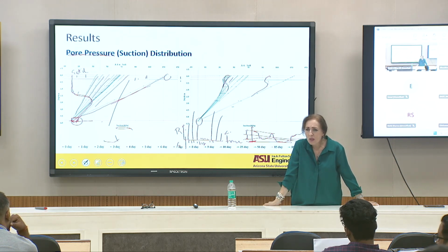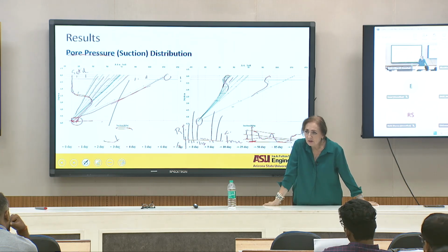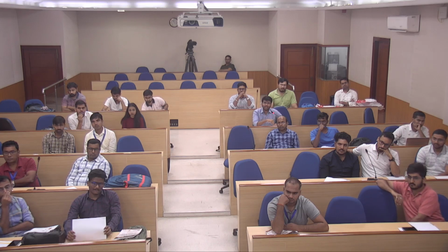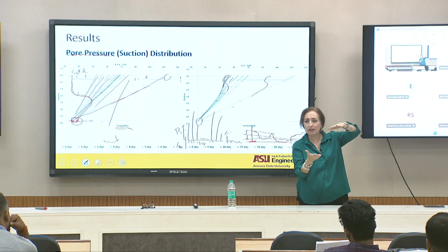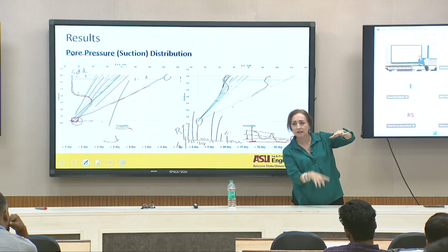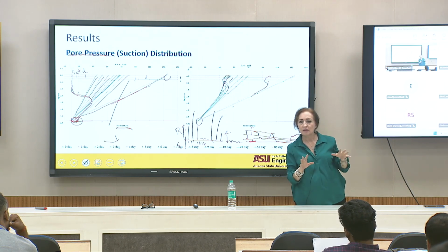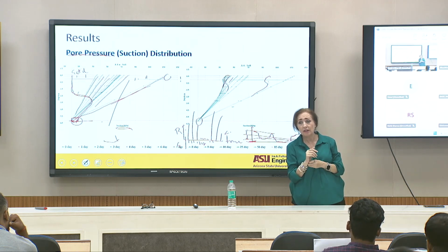And the software, does it allow us to place a wheel load at the top and see what is the deformation we get at the top of the subgrade or something? You're talking about software like MEPDG? Yeah. No, in this Plaxis Studio. In this one, yeah, you can. Well, you still consider the overburden pressure because I put the densities of the asphalt, granular base material, and all of that, right? So I did that, so it will consider that. But if you put any more load, yeah, it is considering the overload.